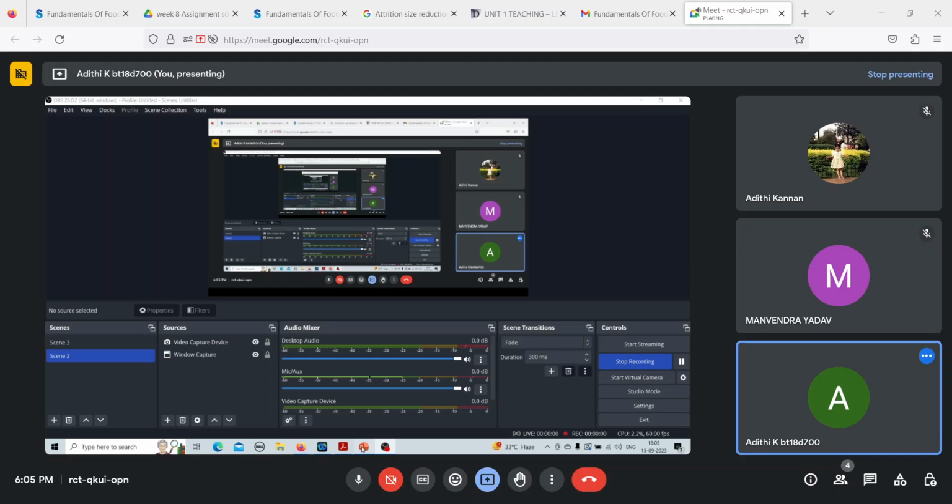No, A is actually correct. So we look at the different laws. As I told you, this is common for all three laws. That is, the energy change required to reduce the size, dE by dx, is directly proportional to the size of the particle. If you remove the proportionality constant, you have a minus c here. So dE by dx is equal to minus c x bar minus m. And this follows the power law model.